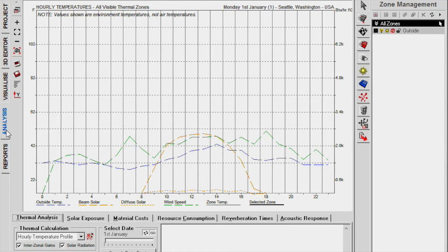So if I looked at the temperature profile in the box across time, it's probably going to start up here at 60, but it's going to start dropping. And why is it dropping? Because you have some sort of differential between the inside and the outside, and heat's going to flow one way or the other. If it's colder outside than inside, heat's going to try and flow out. If it's warmer outside than inside, heat's going to try and flow in. So over time, it's going to start dropping.